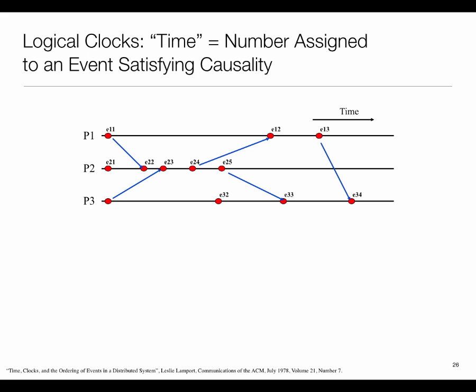So one very common approach to time synchronization is not to synchronize physical time, but rather to synchronize logical time. The idea is, in some of my examples where a sensor wants to know whether it was first or the other sensor was first, I want to get the direction right. All it needs to know is the logical ordering between my timestamp and the timestamp at another node. I don't need to know how many seconds the difference is. I just want to get the order right. And some of the early work really focused on that.